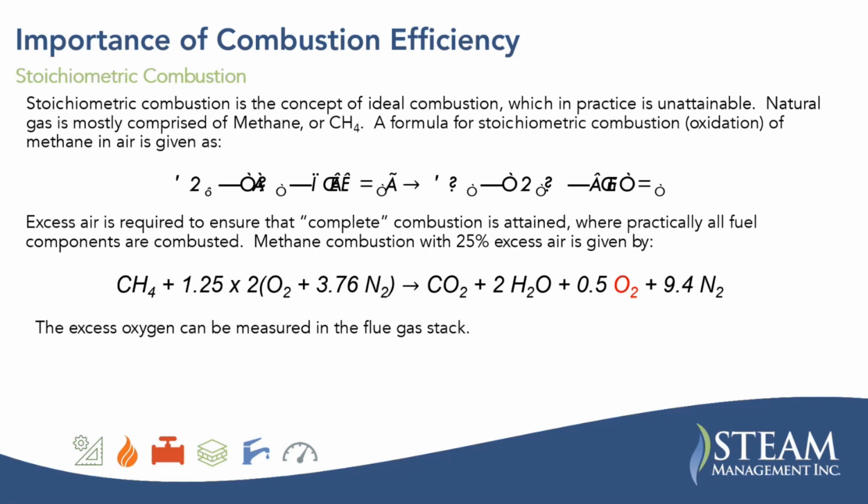This oxygen is what is measured when you're looking at a flue gas analyzer. When you talk about O2 percentage, that's what we're talking about: the extra oxygen that wasn't burned in the combustion process.